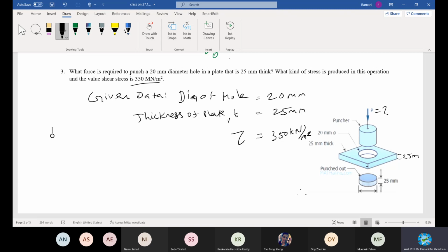There is no elongation, there is no compression; rather the material is sheared due to application of the loading and the material property to shear along the surface, tangential to the loading. That's how you can get the job done for making a hole. The striped lines are the area in action for shearing.